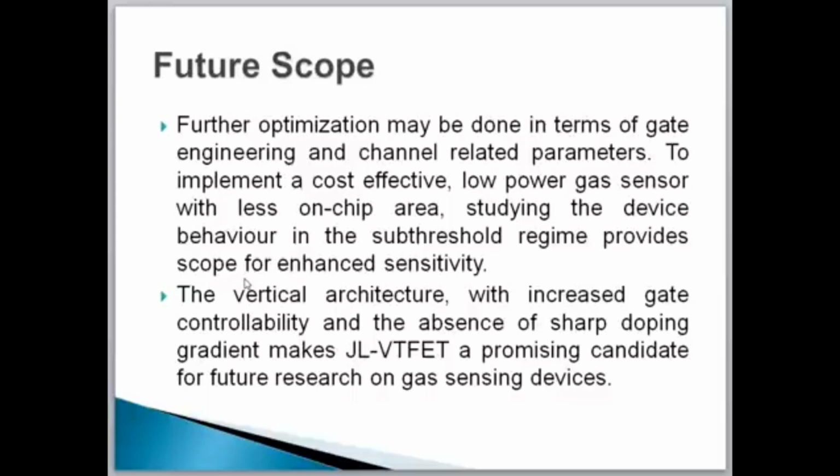Second, the vertical architecture with increased gate controllability and the absence of a sharp doping gradient makes the junctionless vertical TFET a promising candidate for future research on GaN sensing devices.